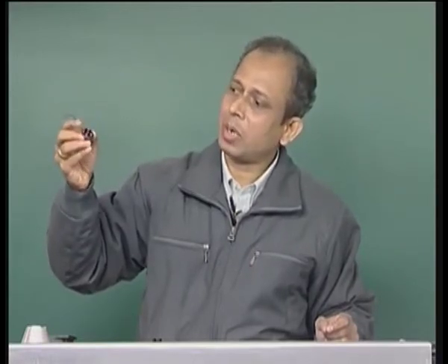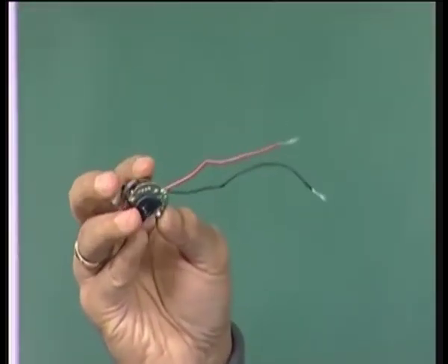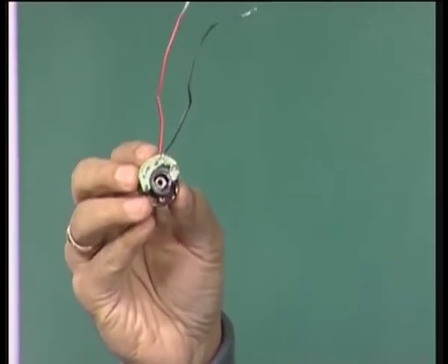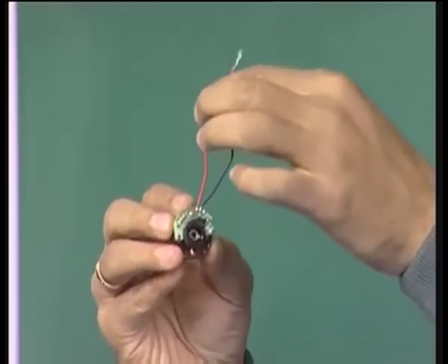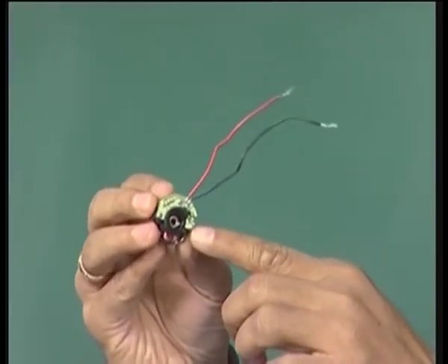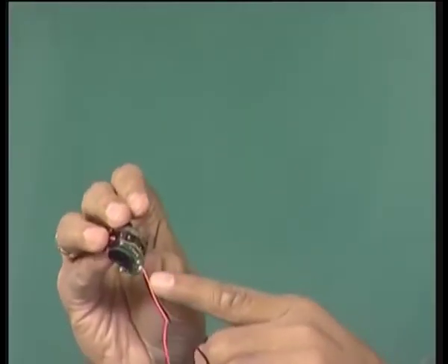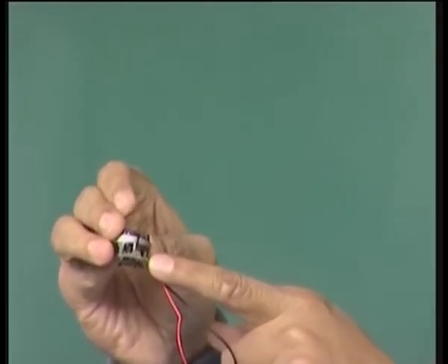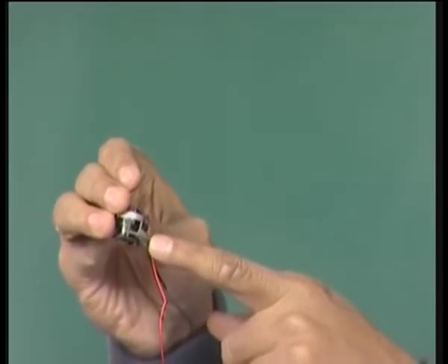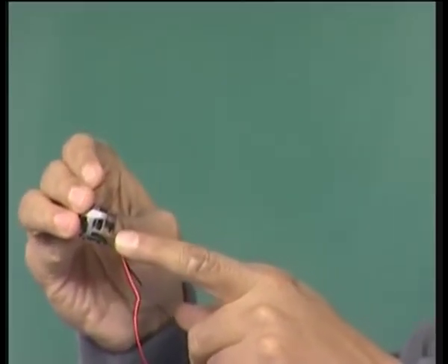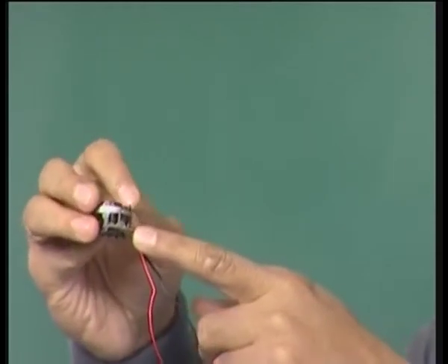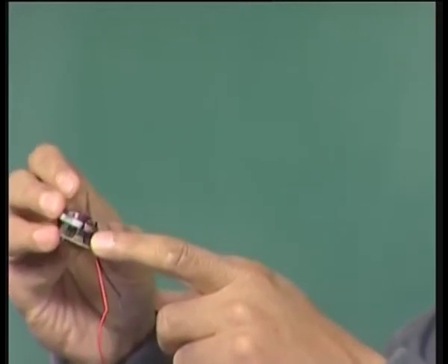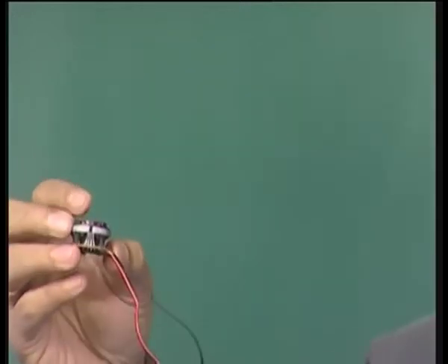And if you see very closely, there is a printed circuit board here which is attached to this stator. It is stationary and connected to the external power supply. So this is the printed circuit board, and in the printed circuit board there are very few components. You can see there is a single transistor structure here, and this has got 4 legs. These 4 legs could be for the 4 windings. Since we have 4 windings, this basically is a power switch, and this will be switching the current to all these 4 windings.